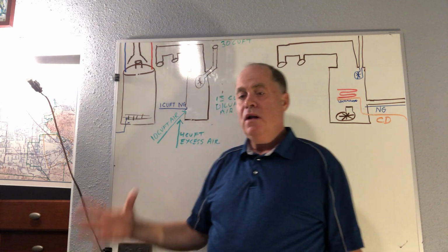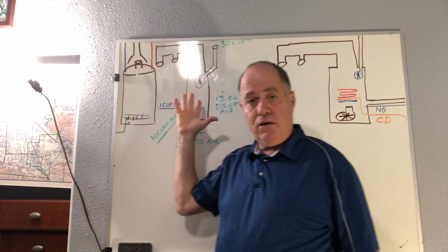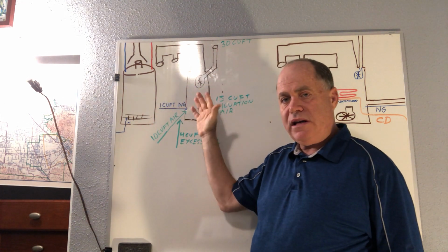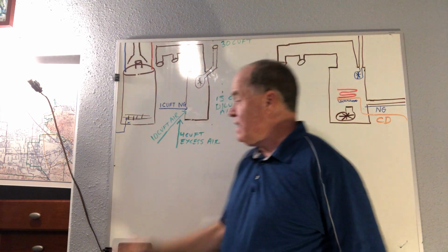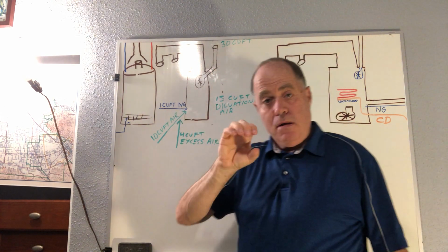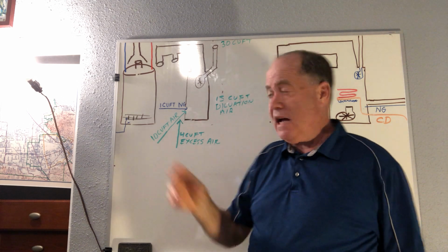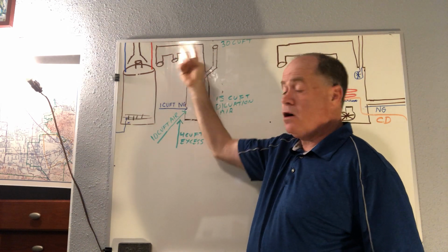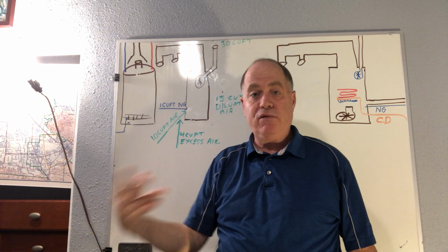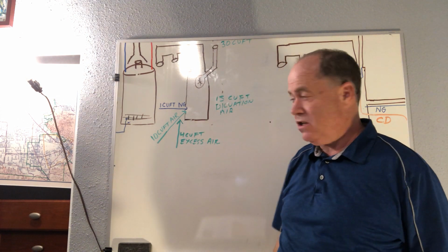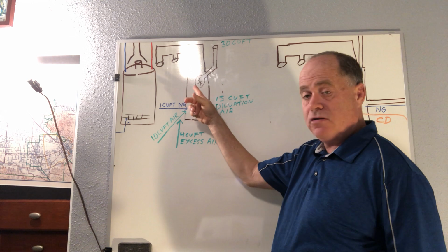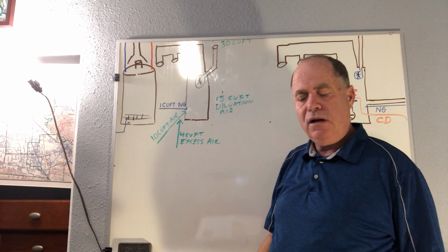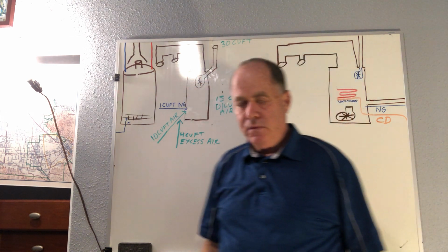But now with the power venter and more modern technology, 82, 83% efficient, if you're using 100,000 BTUs quality of natural gas into your pipe coming out here into your ductwork, you're getting more like 82 or 83,000 BTUs, okay? With this combustion blower, power venter, and more modern type designs.